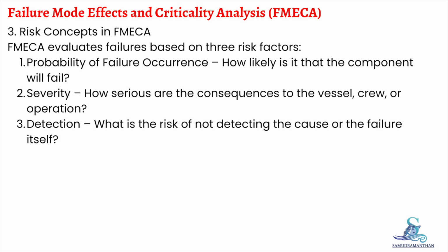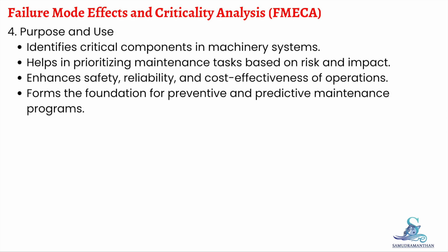By analyzing these three aspects, engineers can identify which components pose the highest risk and must be prioritized during maintenance. The purpose of FMECA is to help engineers identify critical components and prioritize maintenance tasks based on risk and impact. It enhances safety, reliability, and cost effectiveness of shipboard operations. FMECA also forms the foundation of preventive and predictive maintenance programs, making maintenance more organized and data driven.